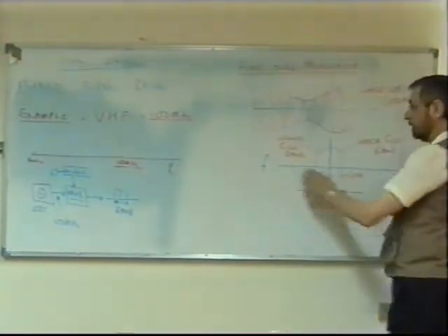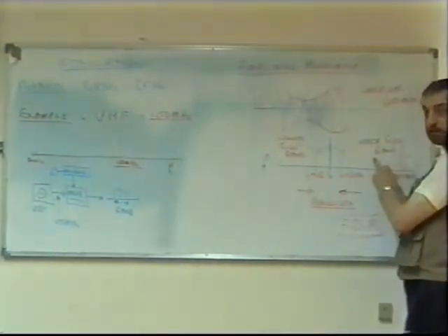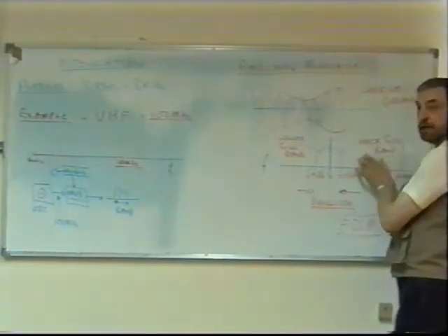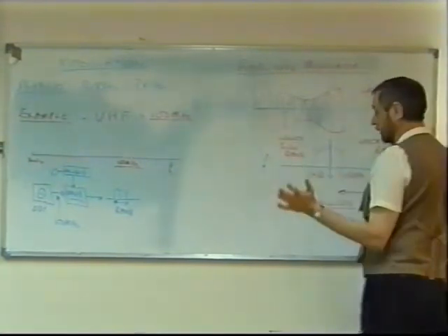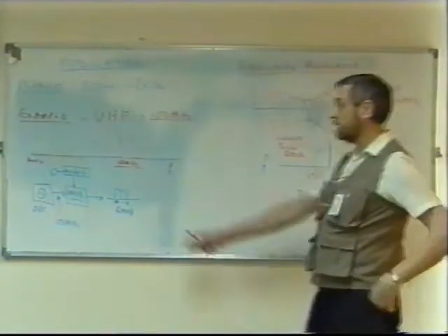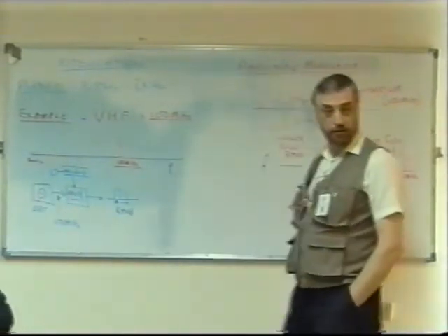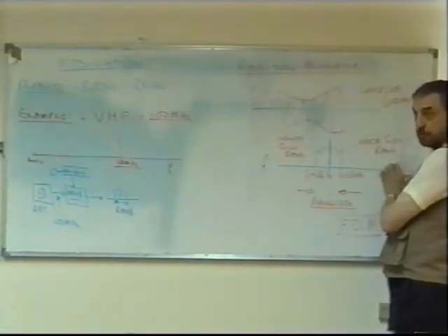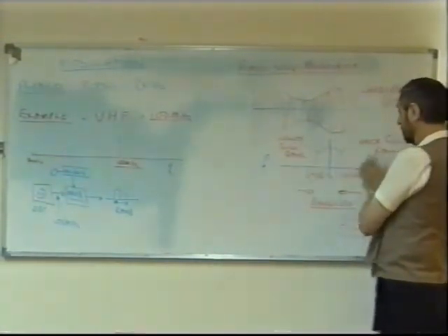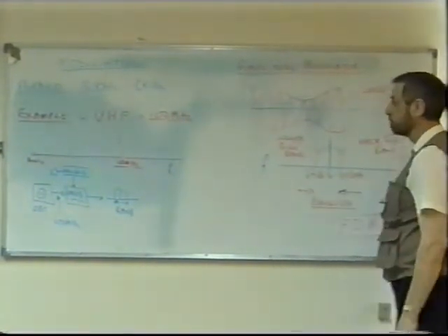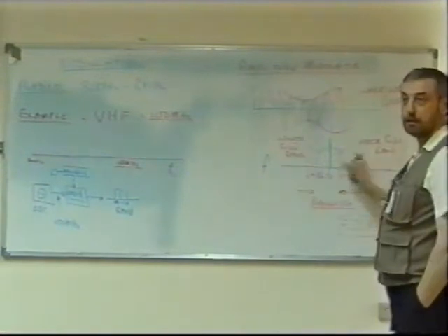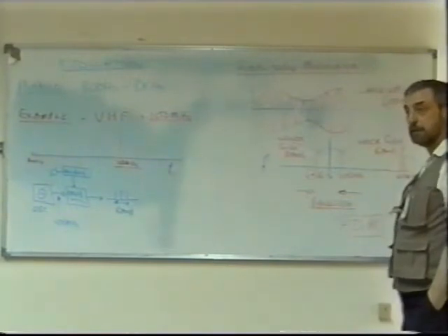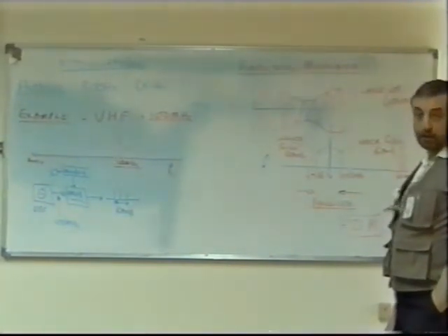The idea being that you can have as many people as you want transmitting on the VHF band, providing each of them occupy a different band of frequencies. Yes. That's the whole idea. And the only way they're going to do that is to make sure that their carriers are different. The width of the band of each is the same. They're all, say, telephone channels. No problem with that. But they mustn't interfere with one another, so each one would use a different carrier. And we can get several channels, a lot of channels, in the same VHF band. Same time as well. Exactly. Same media. Well, we are using the same media.